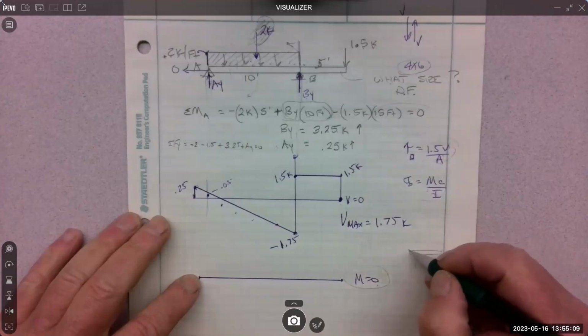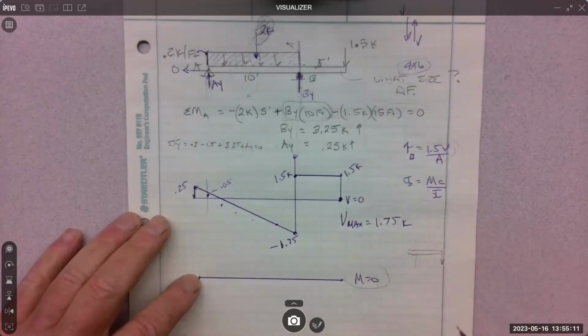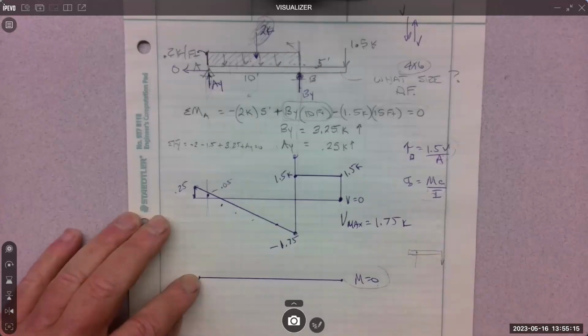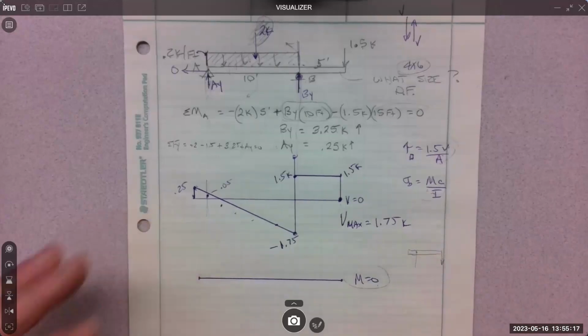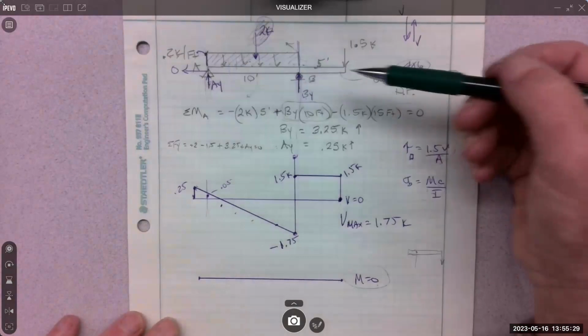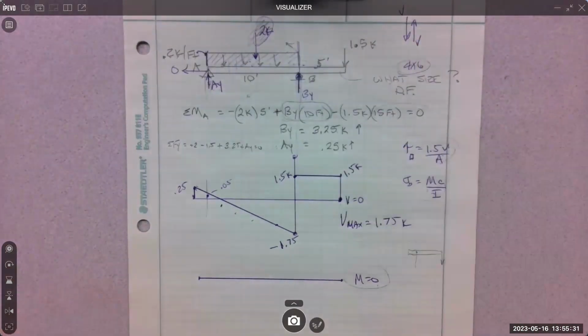The only time that's not true is if you have a cantilever, right? Something built into the wall and you put a load on it. That's a cantilever, big moment right there, right? So that's not a free end. That's an encased end or something. Telephone pole. The end is not free. Like that's what's holding the whole thing up, right? Giant moment down at the bottom. All right. But this beam, what we call simple beams, we like them to rotate. That's a good thing.